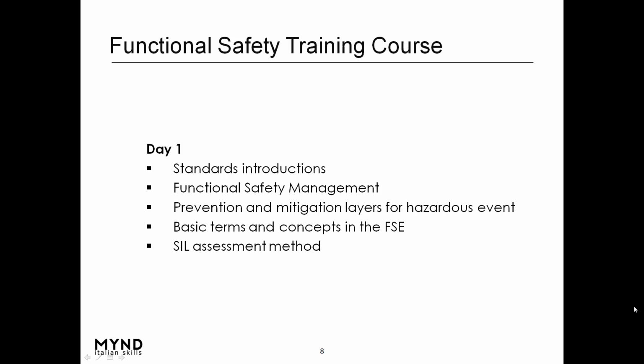Important aspects are the methodologies for the evaluation of the SIL level, where the risk graph and LOPA methodology will be analyzed in depth. Of course, you will also do some exercise, and in particular, when the course is done with the companies, it is very useful to use existing or past projects from the company itself, doing SIL analysis and verification.